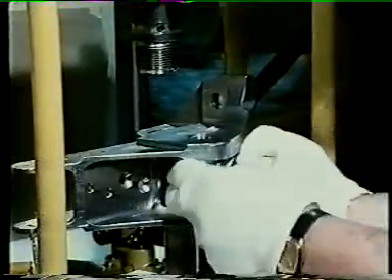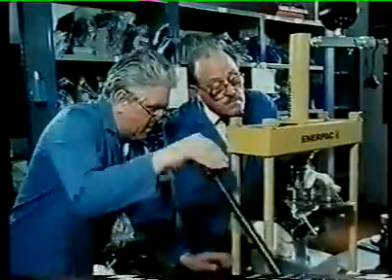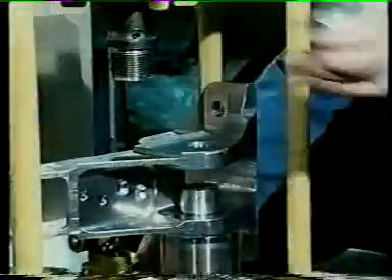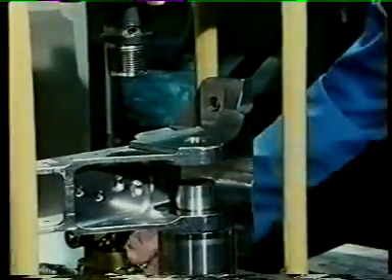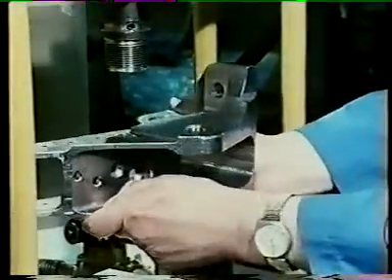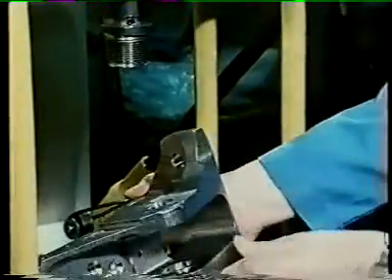Another contributing factor may be built-in stresses caused by manufacturing processes, such as the pressing in of interference-fit bushes or bearings, or by misalignments during assembly. Even items held in store which contain built-in stresses and have been inadequately protected may be issued with cracks in. When it does occur, stress corrosion cracking may proceed very rapidly, posing a serious threat to the integrity of the affected structure.